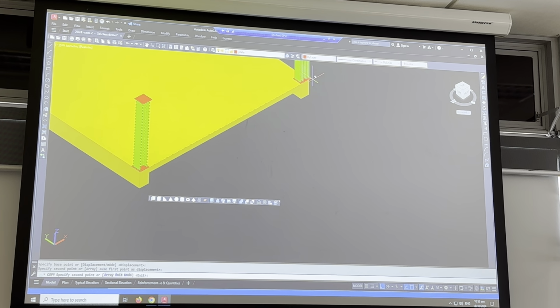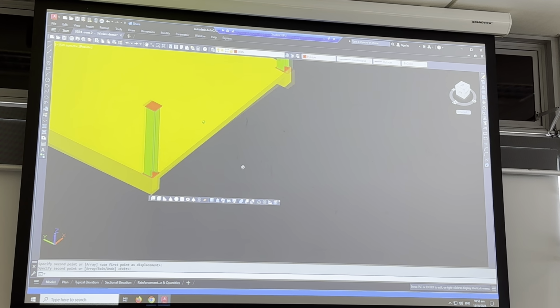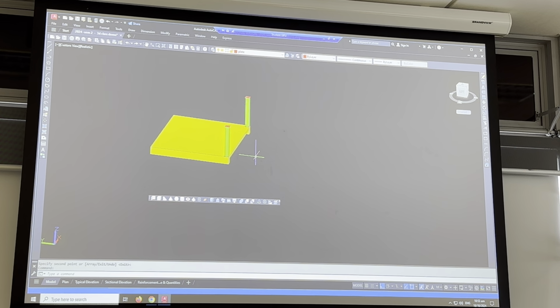Over there. Now, if you're in one of those moods where you think you want to be really cool, you can hold your shift key down and your middle roller and rotate it. And you can even do a mirror if you want to. So I'm going to go MIRROR. Notice I type my command sometimes. I grab all that, enter from the midpoint of here,